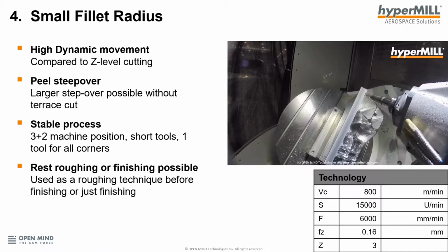Definitely because of the small tool length, you can push the technology values quite high, and so it will give you a really nice surface finish, a very high quality surface and a great result. So this can be used in both a roughing process or a finishing process.